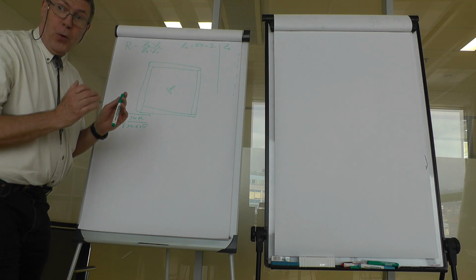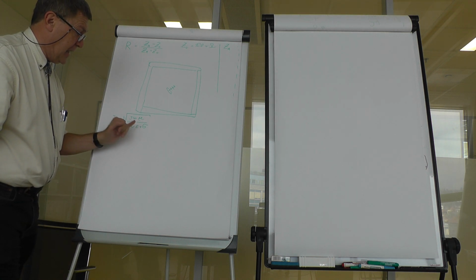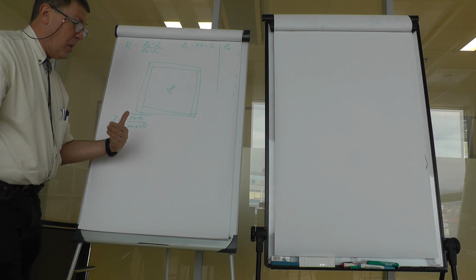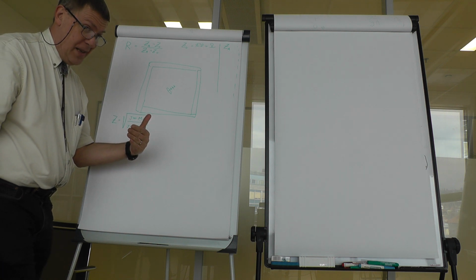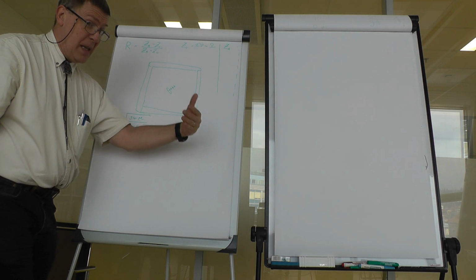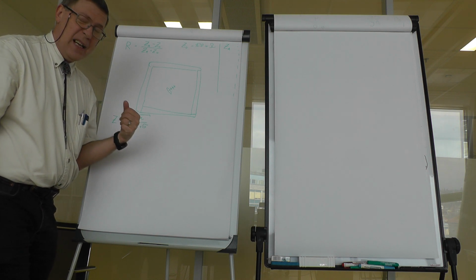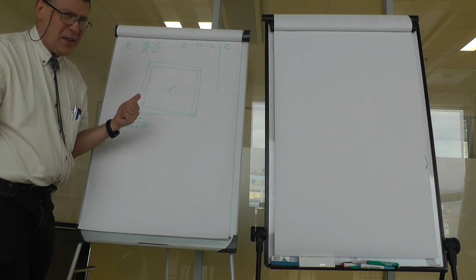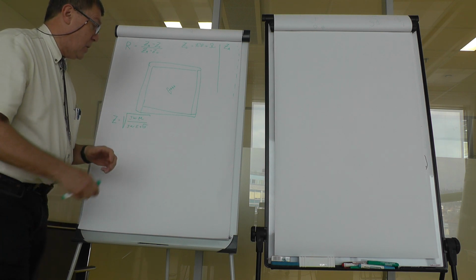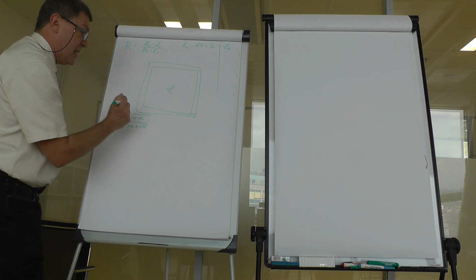It fits quite well for two purposes. First, those three values, permeability, permittivity, and conductivity, are derived out of the behavior of a material, out of its reflection and transmission through that material. And they mimic it very well for most of the materials, except for one kind of materials that are more or less artificially created. We do not meet them in nature. And those are materials that do exhibit both electric losses and magnetic losses.